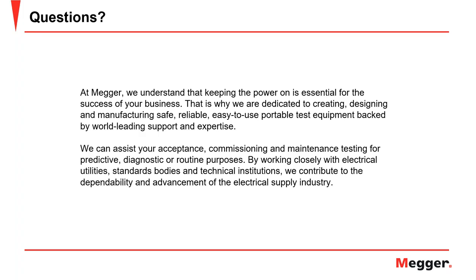Okay, that's a good question. I didn't state that in there. A good rule of thumb is that motors with voltage levels from 2400 V up to 13.8 kV are good candidates for differential protection. But really, any motor or voltage size is good for the protection. It isn't normally used for lower voltage motors, because usually you have to add CTs, the cabinets are bigger, and you need more room. So it almost just depends on how far you want to go with the differential.